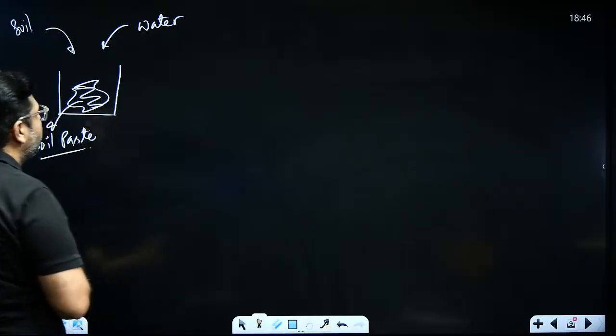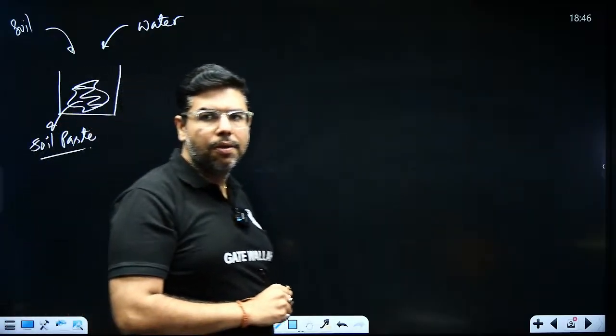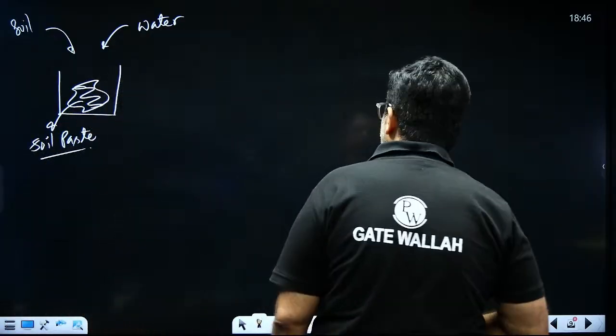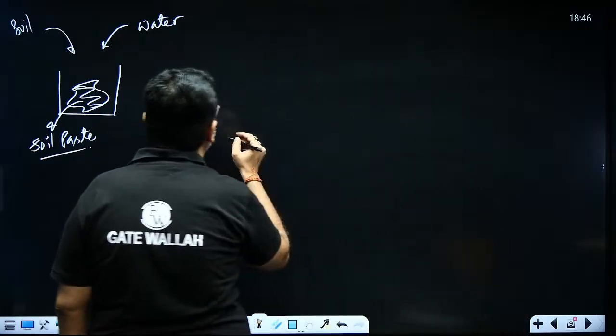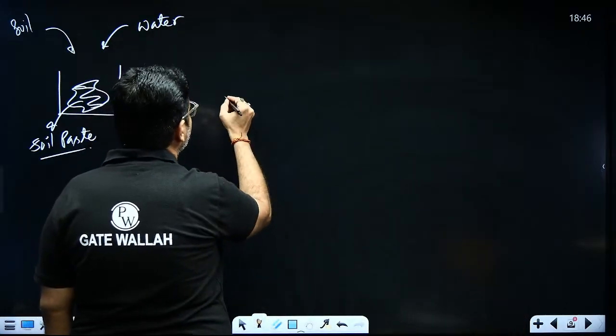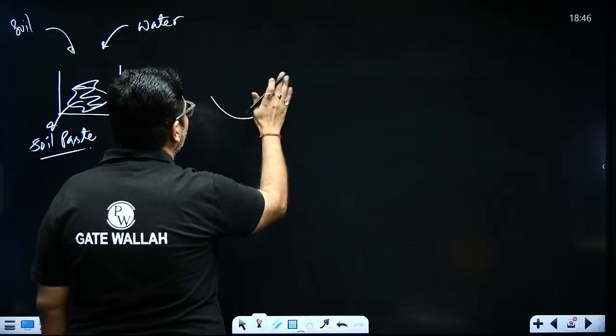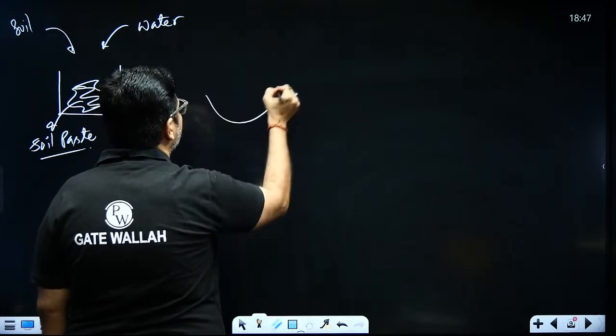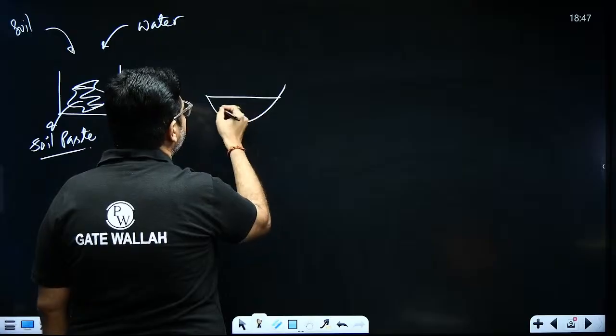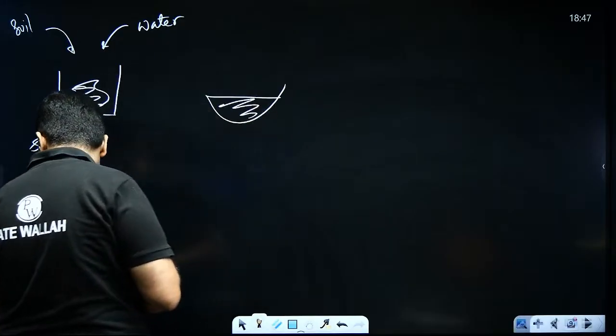And make the soil paste. Now fill the soil paste in the Casagrande's bowl. In the Casagrande's bowl, you will see a marking. Till that marking, fill the paste.